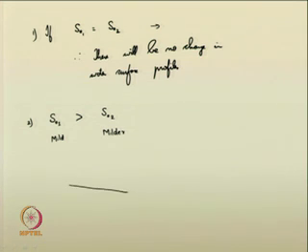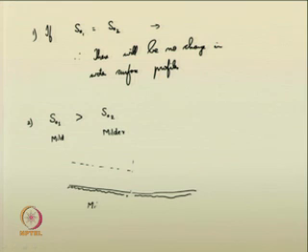So, you can just visualize them, say a mild slope channel, it is having the critical depth, and another mild slope channel, this is a mild slope channel and this is still milder. So, its critical depth is like this, and the mild slope normal depth is like this. Of course, if the slope is less, you know that the normal depth will be higher in this case.